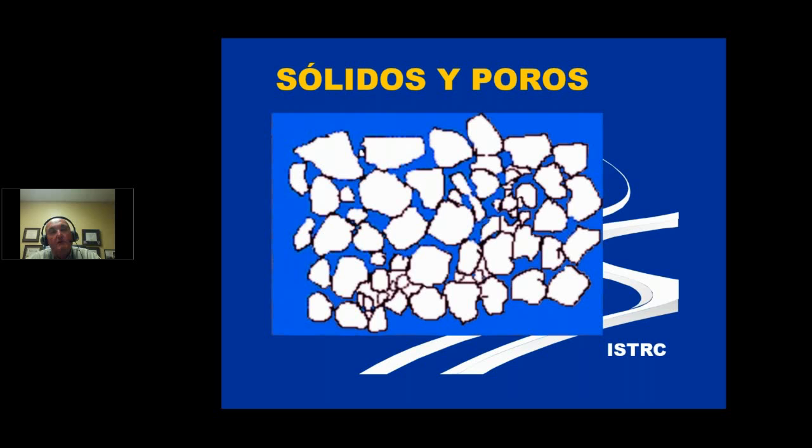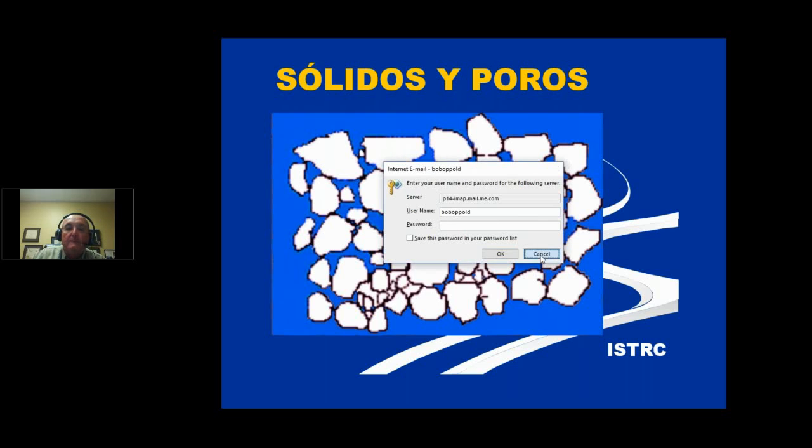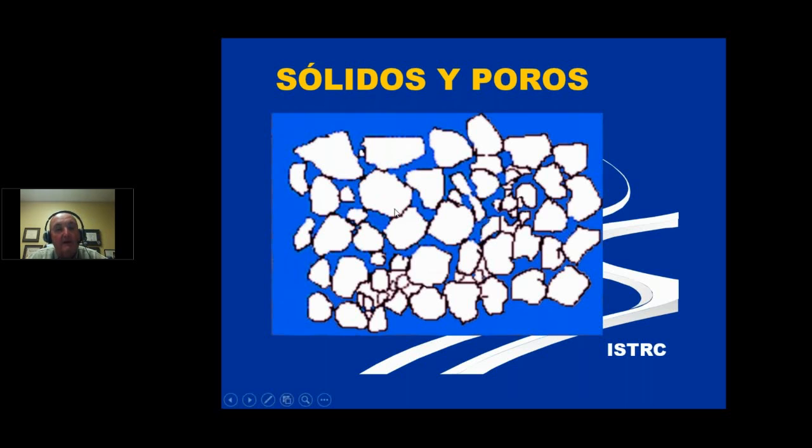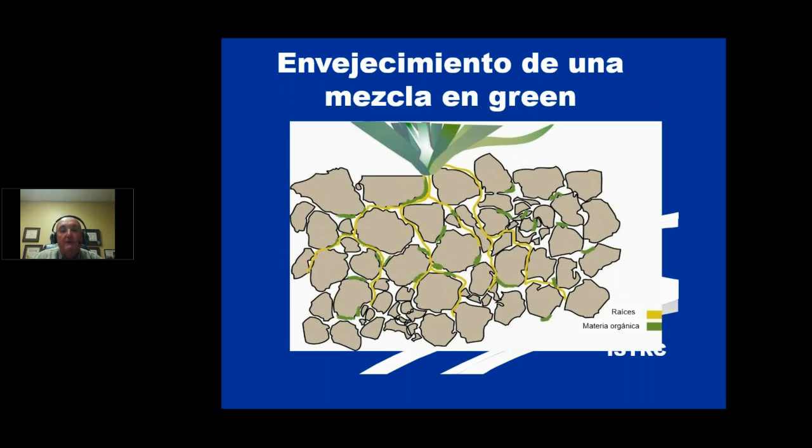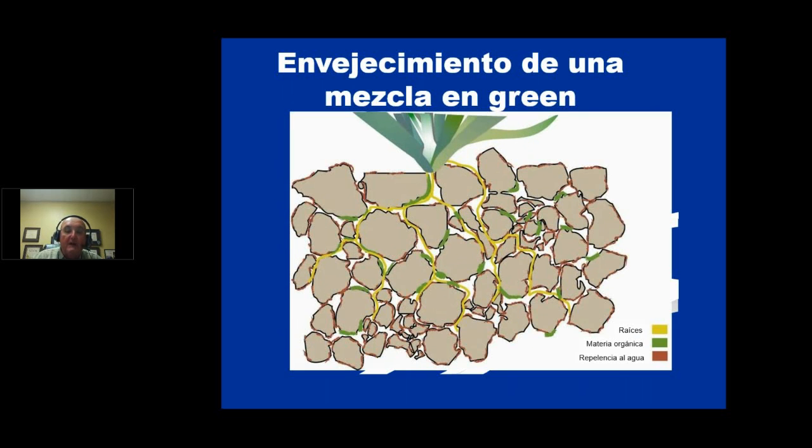So if I have really good evaporation, drawing water out of the soil and quickly drying it, then those medium-sized pores are going to turn into air pores. And if I've got a stagnant environment, then they're going into water pores. And those water pores, like I say, they help drive out the oxygen, and I can't replenish it. So here, remember, we went through the roots and how the system itself is locked up.